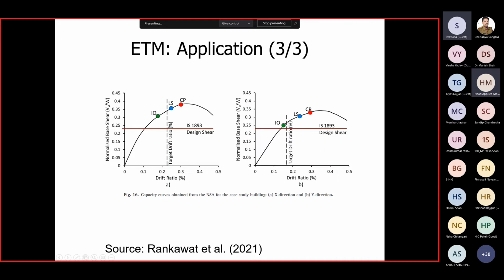possible. This is the capacity of the building on the top, looking at the normalized shear over the self weight or seismic weight. Let's say it was 0.4, and according to Indian standard, it was designed to 0.25. So the building, if the earthquake happens of the intensity corresponding to zone 3 in that location, the buildings would be perfectly elastic. They would not even achieve a nonlinear behavior.